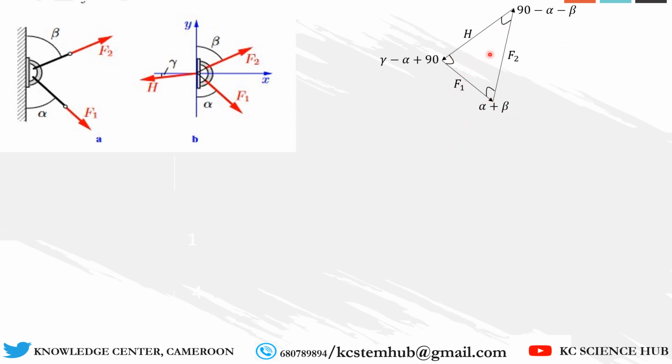Now, the next thing you have to do is indicate the angles between each one of these vectors. It's not overly complicated, but you need to take your time. So if this is beta, this is alpha, what will be the angle between F1 and F2? It will simply be 180 minus alpha minus beta, right? That will be the angle between these two vectors. Now, notice that between F1 and F2 here, this is F2, this is F1, this one is entering this node, this one is leaving this node. So this angle here is not the angle between F1 and F2. You know the angle between F1 and F2, but that angle is not this angle here, right? Because in this polygon, of course, these two are following each other. Okay, good. But here they are leaving out.